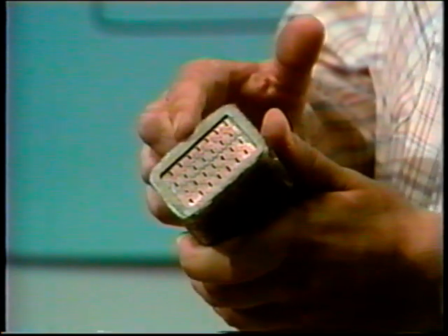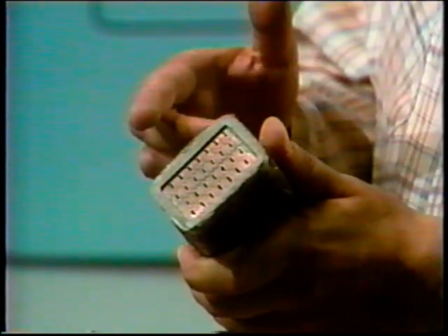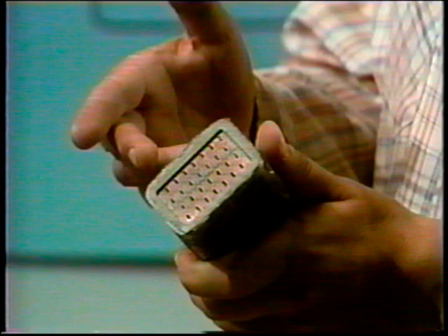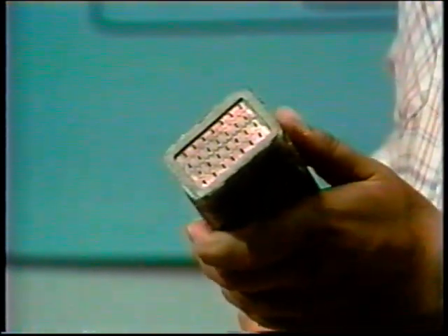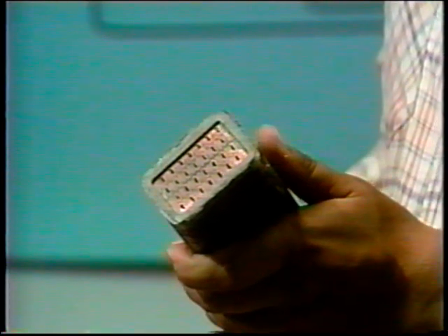In the center, a conductor. Now, as you can see, the conductor has small holes built right into it. When the stator cooling system operates, water flows through the holes and carries heat away from the generator. The water used in the cooling system has to be extremely pure, because impurities would make the water a conductor. So, the water is specially treated before it's put into the system.